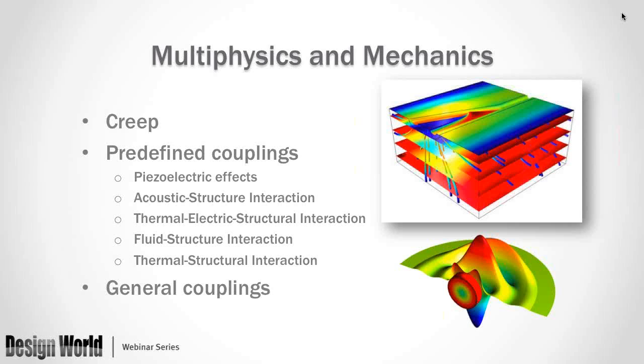Basically, what you do here is you actually solve another equation. The strains become time dependent. There's a strain rate that you need to consider, which is a function of the load, and could be a function of temperature, for instance. And so that creep will affect the way that the stresses and the strains are related in your model. That's something that you can also do using the COMSOL interface.